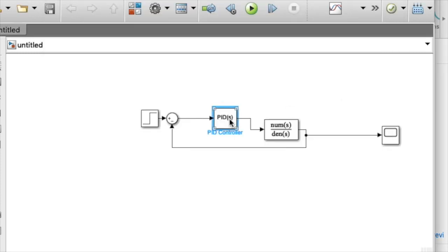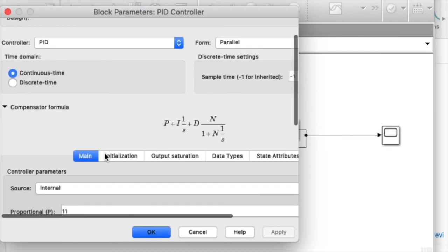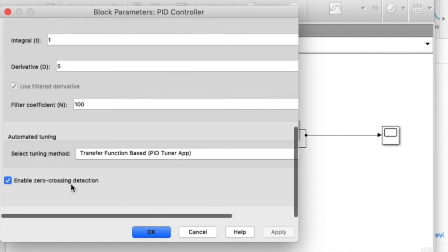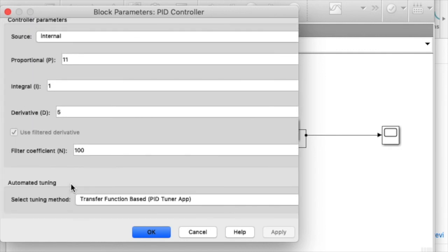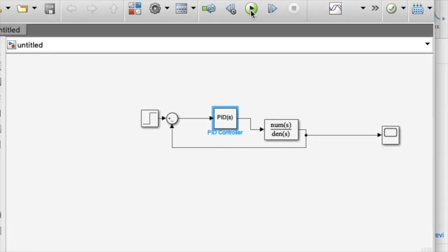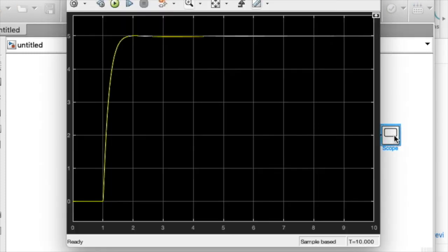So if we increase that again, since if we would have put the integral and derived the equation, we would have a direct solution of ki there as well. But yeah, you see the integral kind of works its magic and provides correction based on that steady state error.